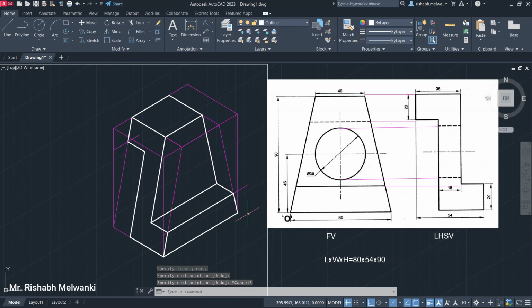So now if we see from the front view we will get this part. Okay, in side view we can see this Z, in front view this line is visible. Okay, both the lines are visible, it is shown by this line. And from the front view if you observe this edge, since it is on the back side it will not be visible, and here we can see the hidden line has been shown.